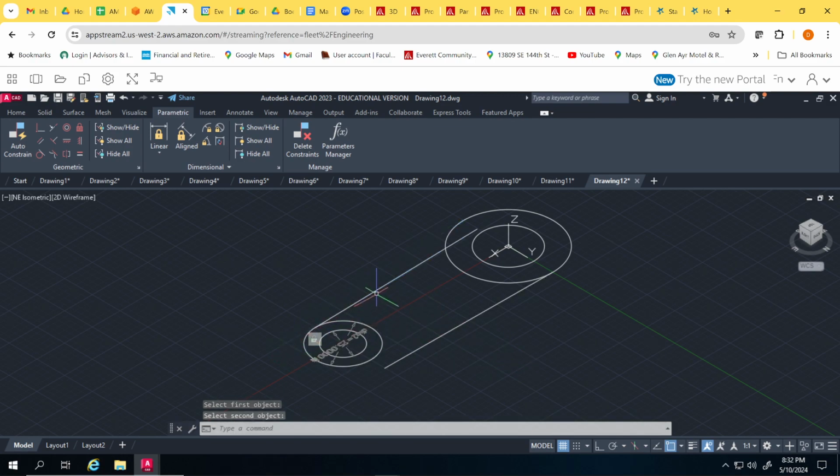and it shifted this one. But see, I got the same problem on the other end. I might as well, enter, apply my tangent line to this, enter, select on this one, make sure it's anchored so it won't move. So I fix it and then enter tangency, select on this curve, and then select this. It still moved. Why didn't I get it fixed?